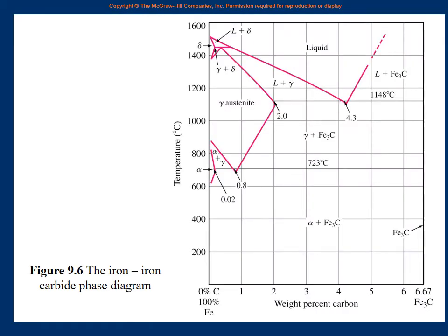You have this diagram, right? We are talking of 0.8% carbon steel. So draw a vertical line here, isn't it? 0.8% carbon steel. It is at some temperature, 750, and we go to just below this line, right? So we are roughly here at this point.